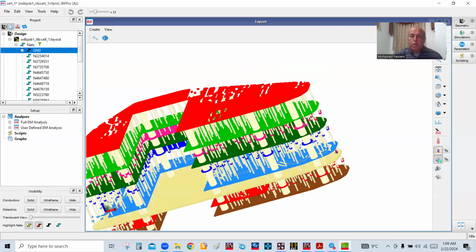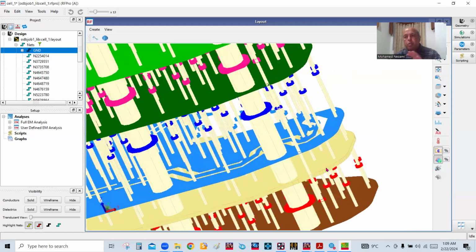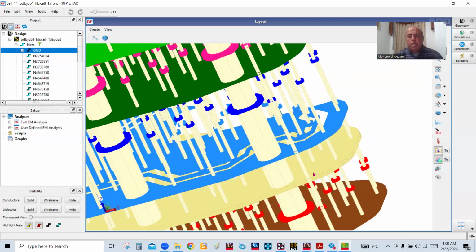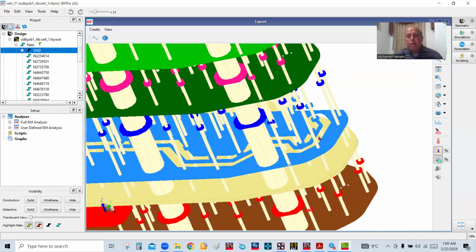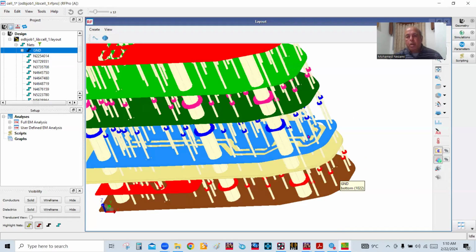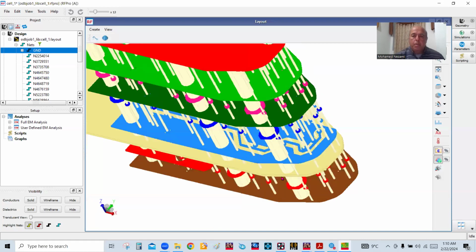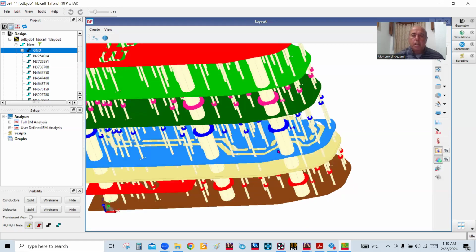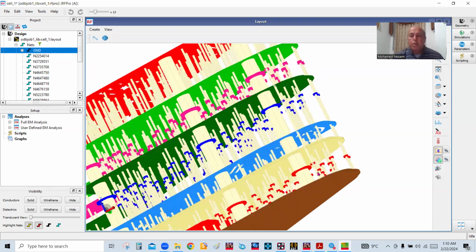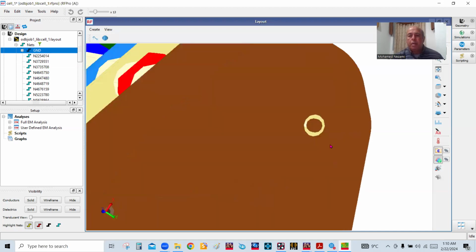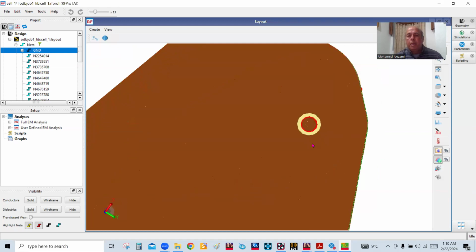Now, one of the issues why we're concerned with this, of course, is that this happens to be running in megahertz. This is the reference for the 10 megahertz. Even though we're coming to the 7th layer in here, the via continues downward. So you have an open stub in here. I have some videos on that using HFSS analysis on designing transitions in a stack layer. But this via here will go from 7 to the bottom, and you can see it's clear from the ground in here. So it goes to the bottom of the board right here.